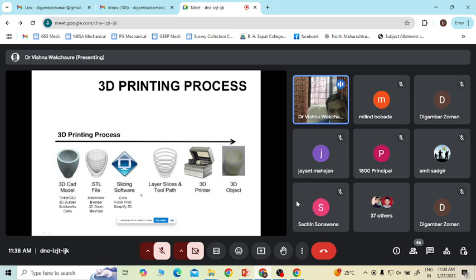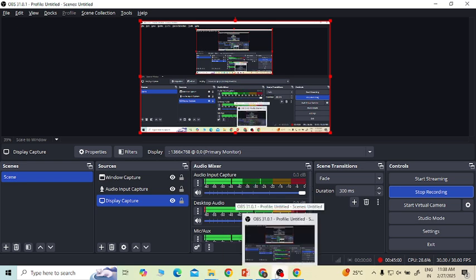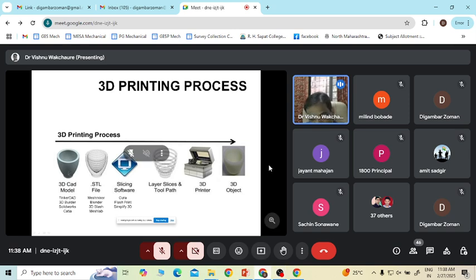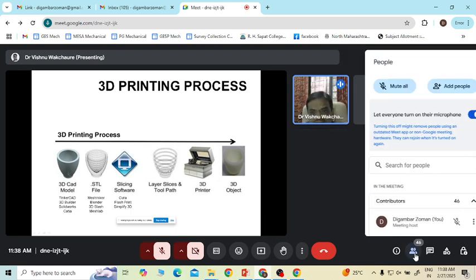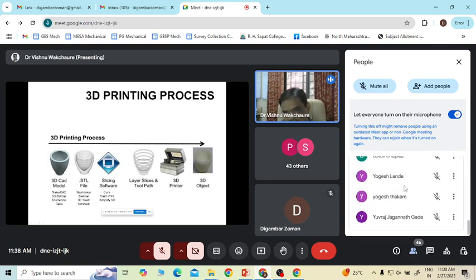So Cura is one of the famous slicing software, right? What we require is data, layer by layer. Here you can see this product is an .stl file, and the manufacturing will be layer by layer, right? In order to lay this particular layer on the downstream layers, you need to control the nozzle as per the shape, size, and coordinate values, right?